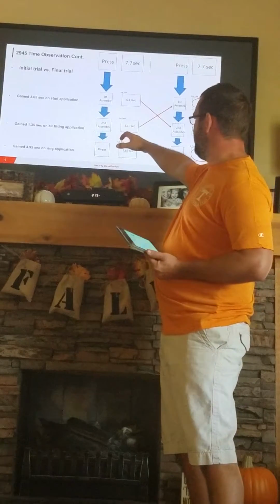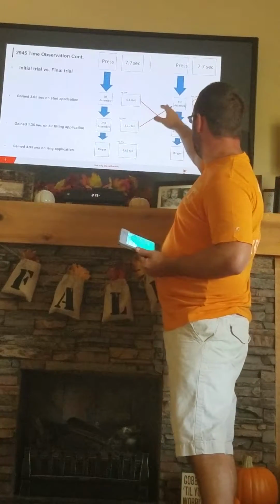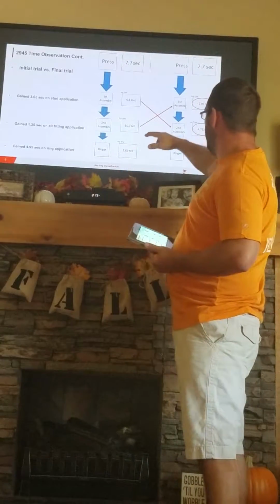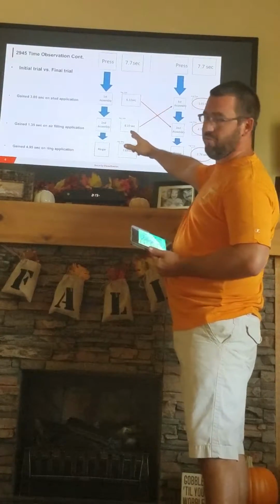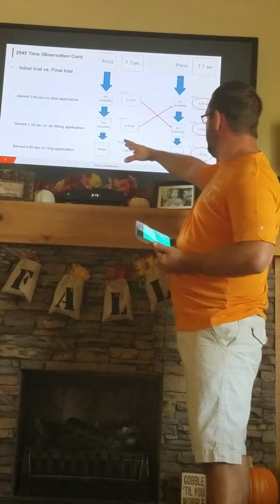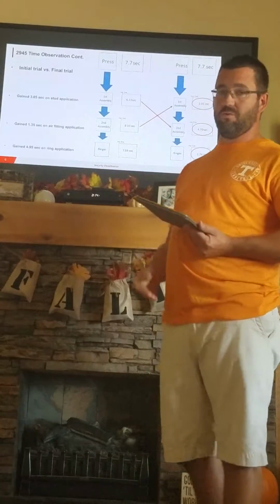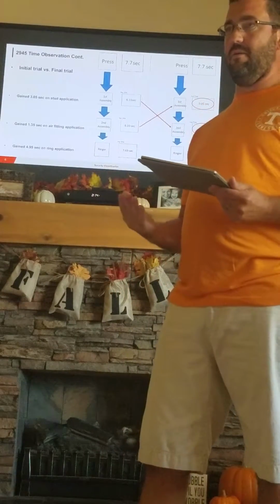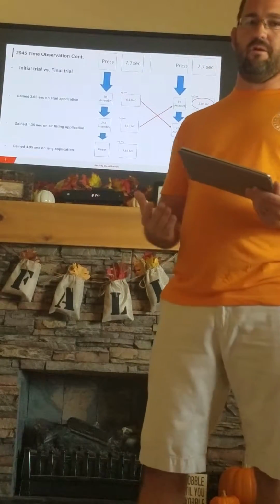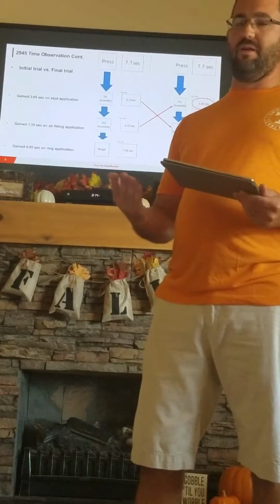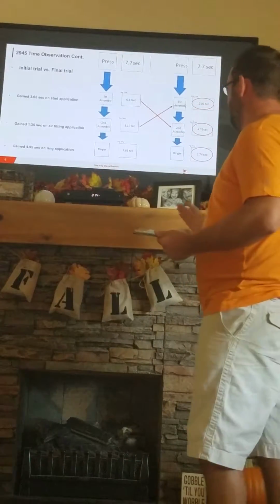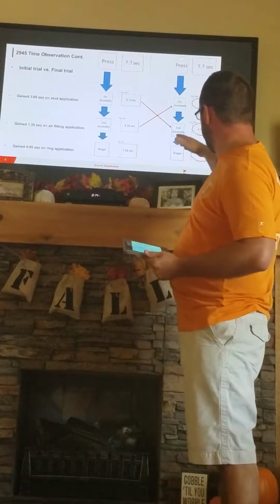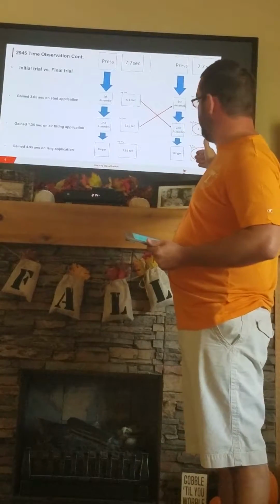From the stud application, moving it from second assembly to first assembly, adding the fixture, the backstop, we gained a shade over 3 seconds. The ringer, by going to the larger diameter ring, along with the rebalancing of the line, the second assembly being able to help them out some now, they were down from 7.7 seconds to under 3 seconds now.